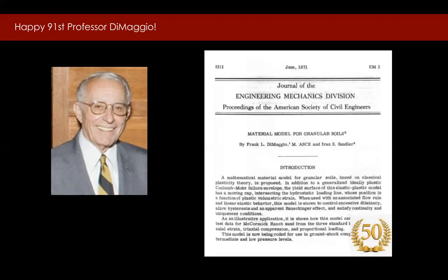The novelty with Dr. DiMaggio's plasticity formulation is a cap that can move under both compaction and dilation. This feature makes the model applicable not only to static loading but also to dynamic conditions, such as earthquakes or an explosion. The movement of the cap is now understood to be a result of hardening or softening induced by compaction or dilation. At that time, such an advanced model would not be practical for manual calculations.